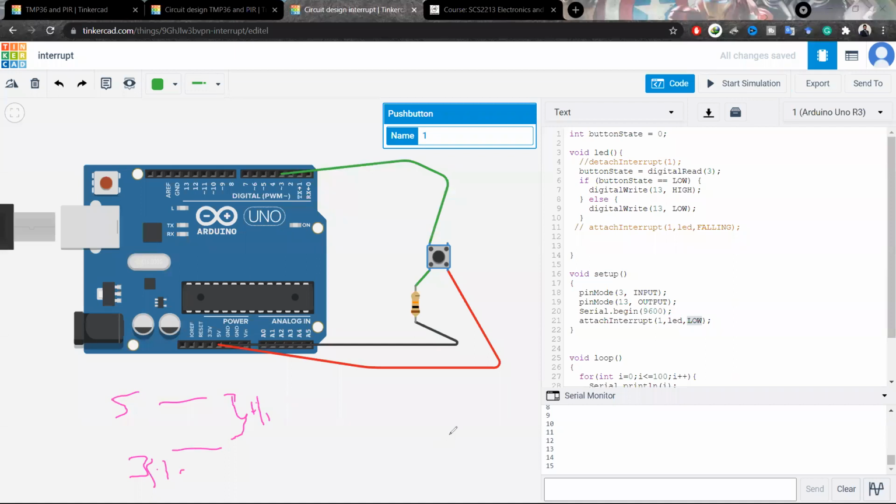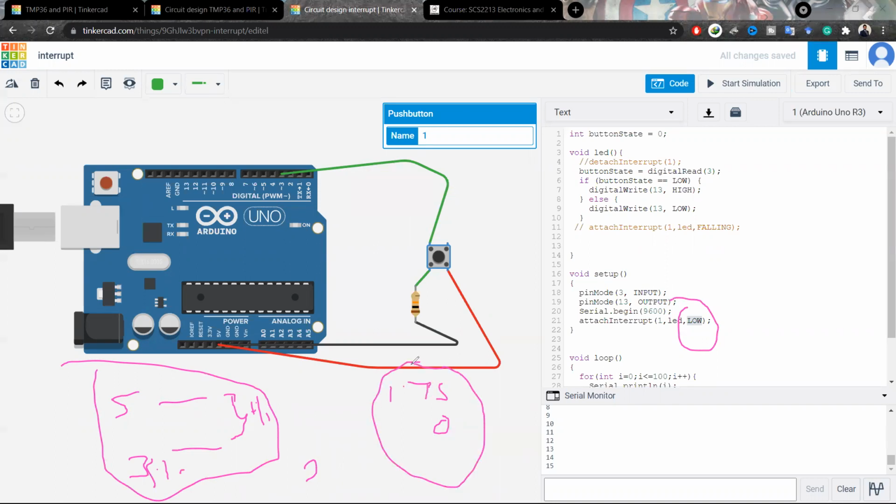So the issue was that this value is not low. Even if we didn't give any inputs, it has a certain voltage, suppose 2 volts, which is in the high range. For the low voltage, it is 0 volts up to like 1.7 or so, and this area is considered low. I think this condition did not occur because there is some voltage inside these pins, so it won't trigger.